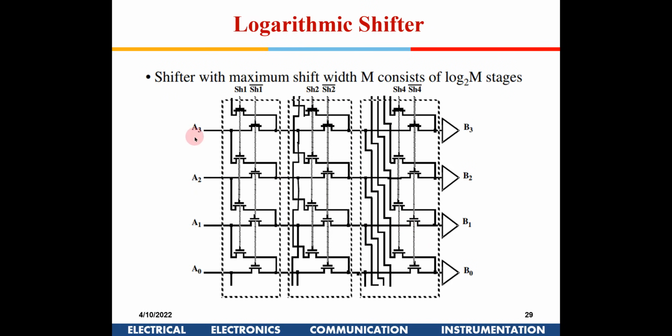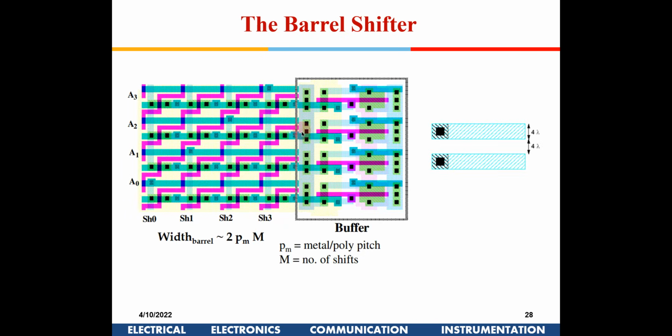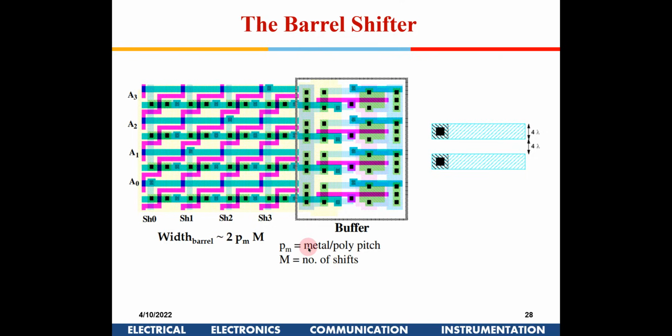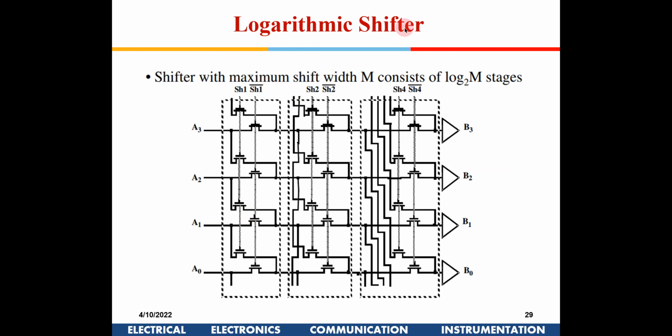Okay, you could also have a logarithmic shifter out here. What a logarithmic shifter is: here, for each shift I had one bit, right? In this shifter, 2 lines going high has not been catered for. Only one line has to go high. So you require a decoder here, and then you can have only one line going high. But this is not the case in the logarithmic shifter.